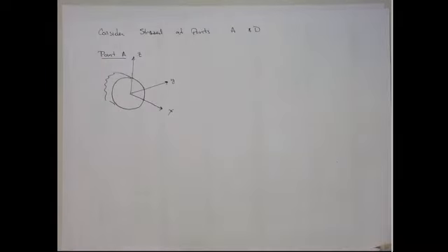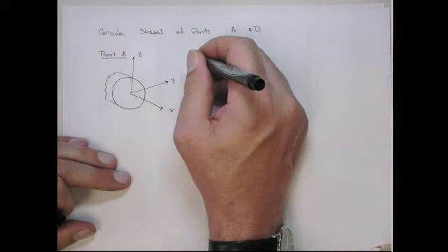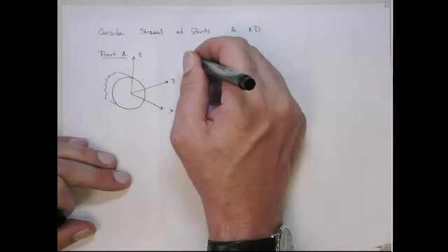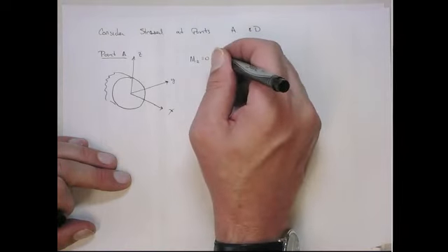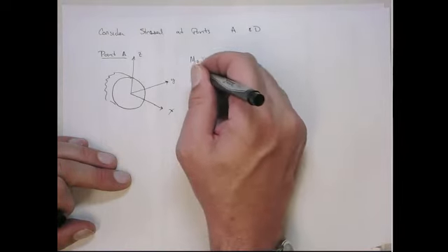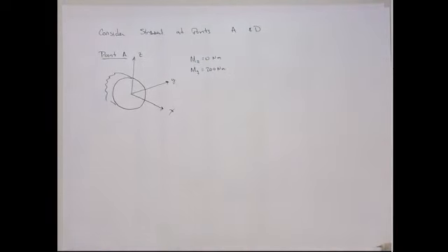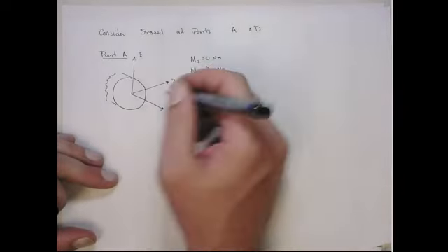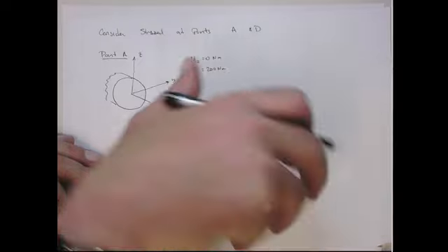All right. So at this point, we have a bending moment about the z-axis equal to 0 Newton meters, and the bending moment around the y-axis is 200 Newton meters. So actually at this point, we really just have one contribution of stress. It's really only due to this, the bending around the y-axis. So that means I have a bending moment like this.